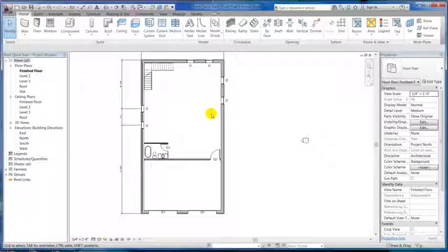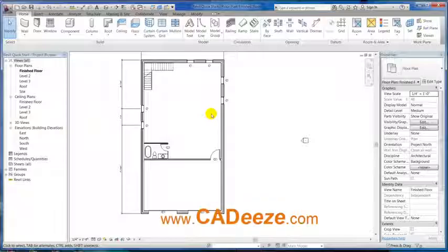Let's see, I also want to get into file types. There's four different file types in Revit. There's an RVT, which is your Revit project. That's your main model. You've got your template, which I talked about briefly. You want to create your company template with all your settings. That's an RTE extension. You've got RFA, which is your family, which we just talked about, and those family templates I just showed you are RFTs. So those are the different file types in Revit. But just remember, your model is your RVT. That's your main one.